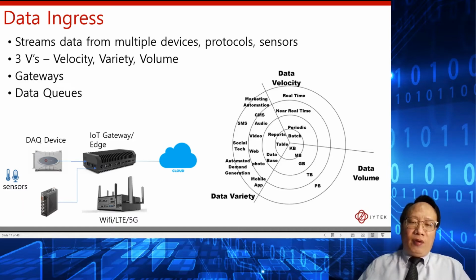If you have data coming from a sensor like temperature, which doesn't change much, for example for smart homes, per day you might be getting kilobytes of data for one channel of temperature or humidity measurements. However, if you're measuring sensor data coming from a microphone or sound, you could be measuring at least megabytes or gigabytes of data. And with data coming from images and cameras, at up to 30 or 60 frames per second, you could be dealing with terabytes of data per day, right? So again, these are the three parameters to look at.